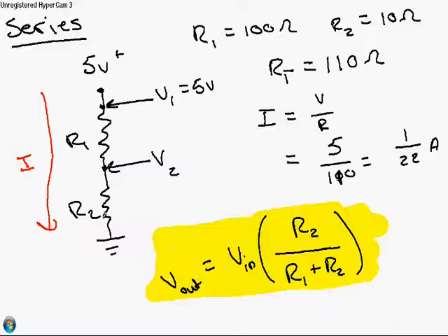So just keep that in mind. We will talk about that, and there is a way to deal with that, but for now, don't worry about it. If you're doing something where you need a reference voltage for like an Arduino or an op-amp, this is the perfect thing. But if you don't, again, those are high impedance things, which we're not going to talk about. Well, I'll have another series when this is done, but we're not going to worry about that right now. Voltage divider, very useful to know.